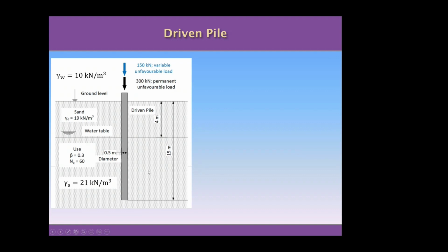The idea of this problem is to determine if this pile is in good condition or if we need to redesign the pile to have a better capacity. So we need to compare the total load we have and whether this soil is able to take all the load that the pile is going to spread. Because remember that in geotechnical engineering, we are not designing the pile itself. So we are not checking the stresses on the pile, on the reinforced concrete, for example, of this pile.